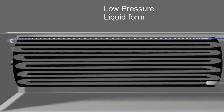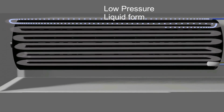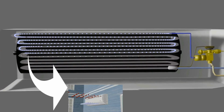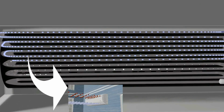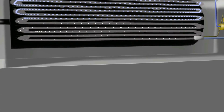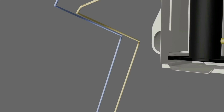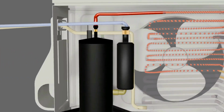Liquid refrigerant is passed through the evaporator at a low pressure. This pressure is so low that liquid refrigerant can't stay in liquid form. And when it evaporates, it requires a lot of latent heat of vaporization. And the refrigerant absorbs this latent heat of vaporization from the air of the room. Refrigerant therefore changes from liquid to vapor form. When the refrigerant exits the evaporator and enters the compressor, it has low temperature, low pressure and consists of slightly superheated vapors.